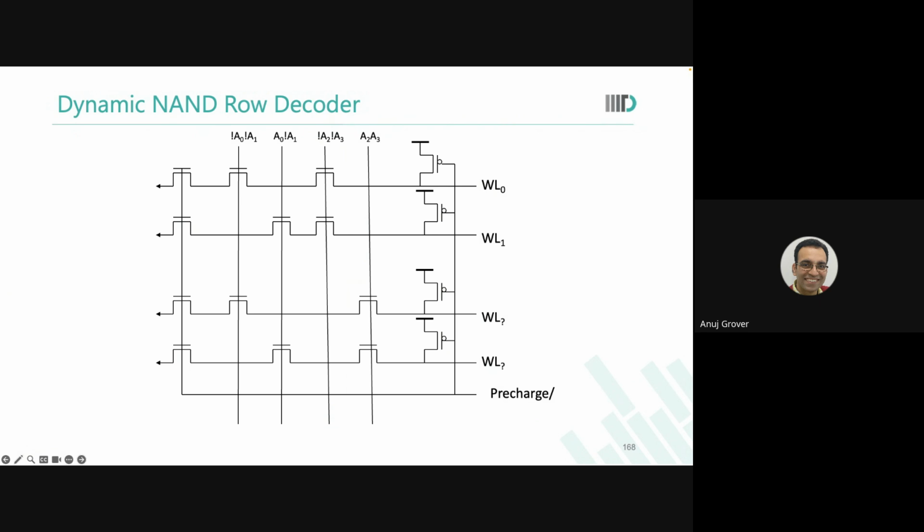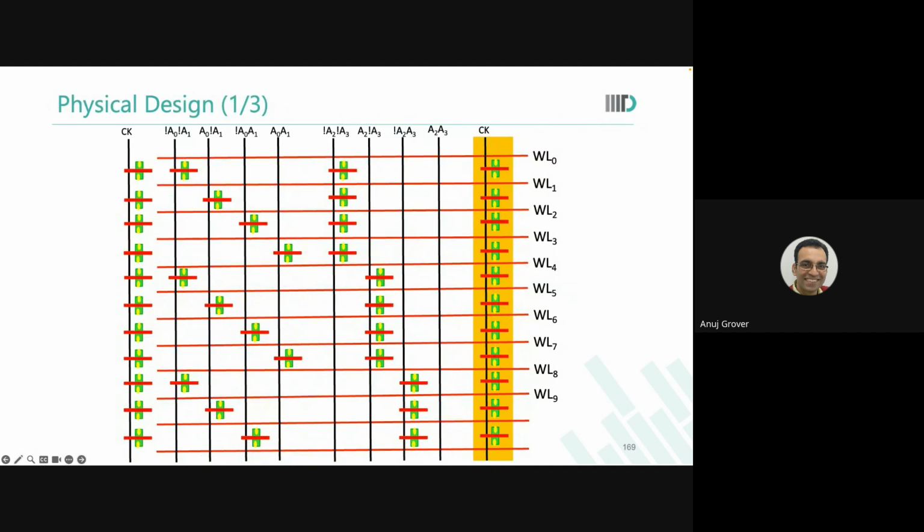Are you with me? So there is a lot of metal one that you will need to route to connect these transistors, which you have presently just placed randomly according to the programmation. So while it appears that you just have to place a device here and there, realize that there is a lot of metal 1, metal 2 jugglery that you will have to do alongside placing these devices like this.